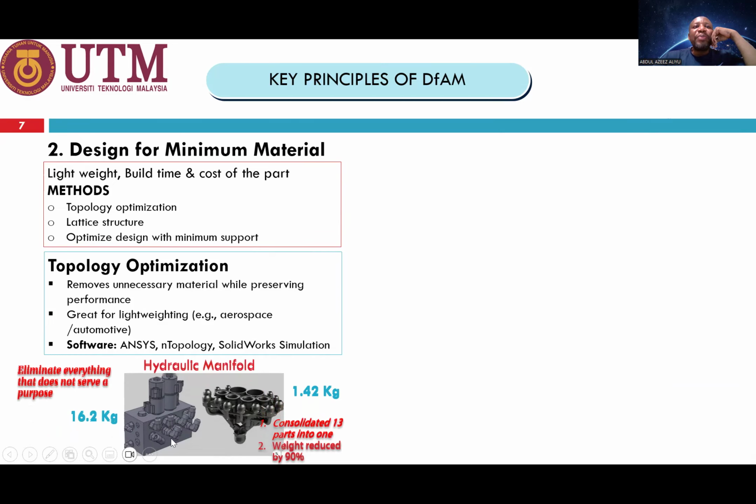All these components were redesigned and produced using additive manufacturing and consolidated into one part. So you can see that you consolidated 13 parts into one, and the weight was reduced by about 90%, from 16.2 kilograms to 1.42 kilograms.